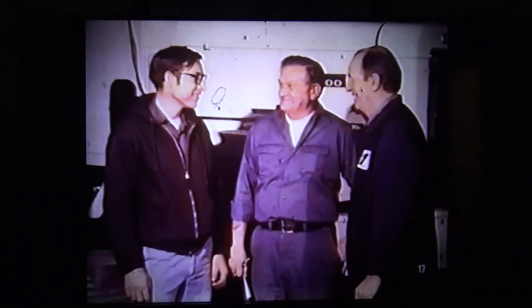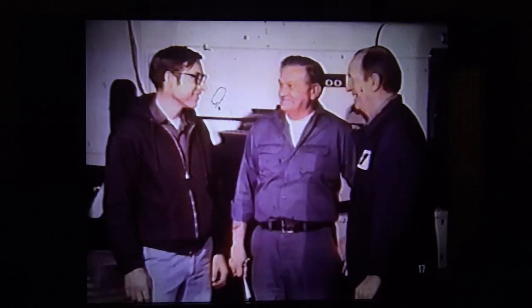First, thoroughly interview the operator. Often, he may have an idea what the problem may be. Examples of questions he should be asked include: when does the vibration occur? At what RPM range? Does it occur under load or when coasting? Then inspect the vehicle for obvious defects. Look for broken or loose cross members, broken or loose engine and transmission mounts, defective suspension torque rods, spring U-bolts, or propeller shaft U-joints. Any obvious defects should be corrected before you proceed.